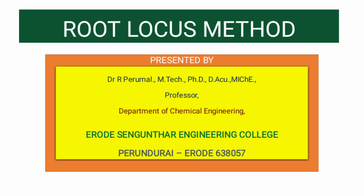If any one of the coefficients is negative or 0, the system is unstable. Next, the sufficient condition: if the necessary condition is satisfied, all the elements in the first column of the Routh array must be positive. If any one of the elements in the Routh array is negative, the system is unstable.